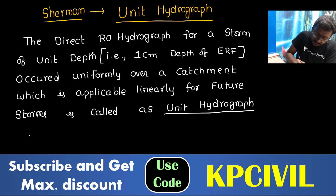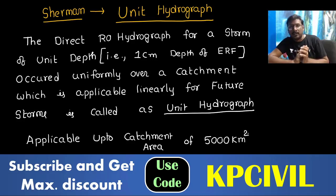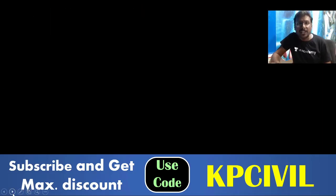This unit hydrograph is applicable up to a catchment area of 5,000 square kilometer, not more than that. If the catchment area is more than 5,000 square kilometer, the unit hydrograph is not at all applicable. So how can you construct UH ordinates?